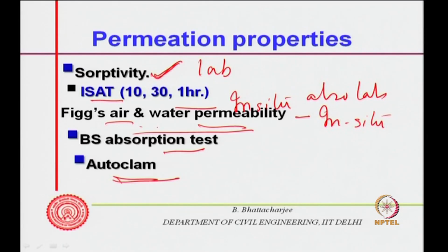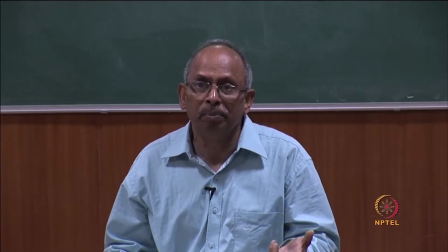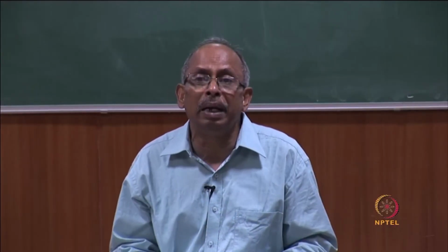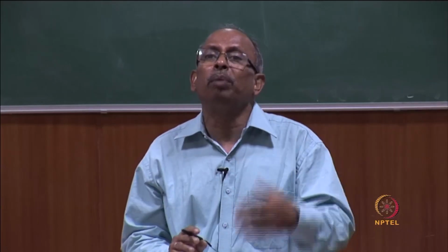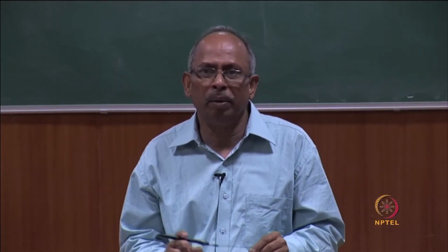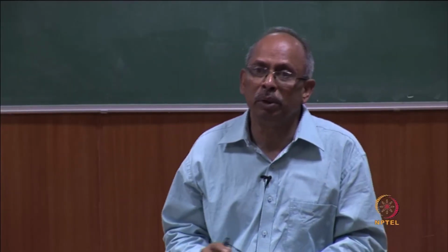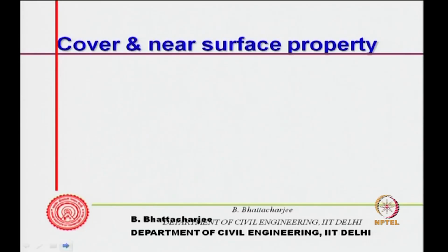So, there are several of them which are there, and some of them can be used in situ, not on the lab specimen. So, that you can find out the durability performance of concrete in structure. Permeability is difficult to determine, but these ones will be relatively easier. But with this one you can actually compare two different concretes, but cannot predict really much, they are not predictive, but you can tell which is better concrete, which is poor concrete.